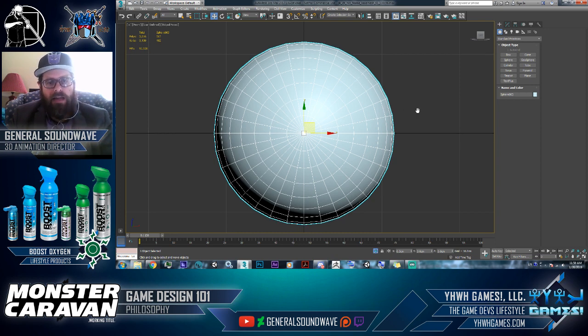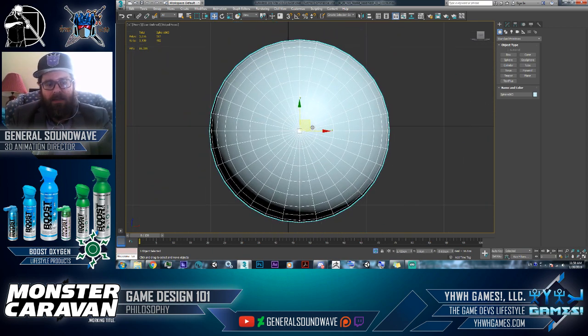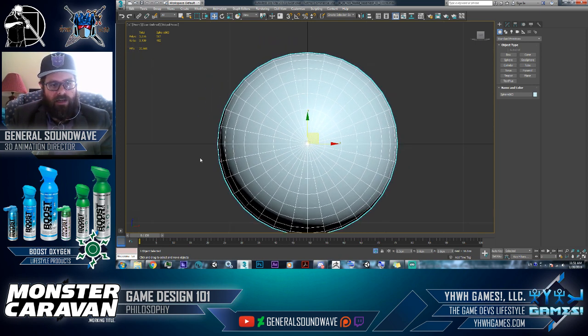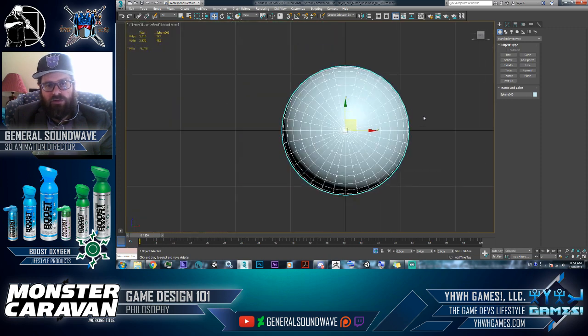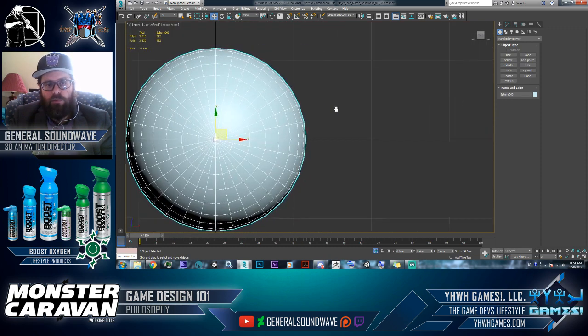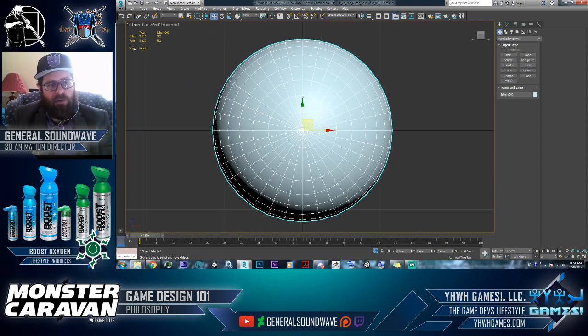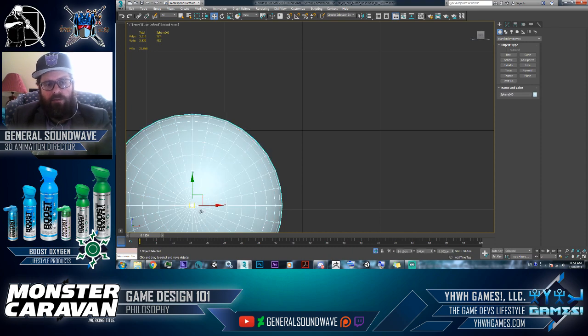All right, so now to pan, to move the camera. Now I'm not moving the object. This is moving the object. Now how do you know when you're moving the object or you're moving the camera? Easy. There's this grid over here. This grid is actually really helpful. If you press your middle mouse button and start moving it, not wheeling it. Now if you wheel, it's going to zoom in and out, okay? But if you press it and move the mouse, you're now moving the camera. This is what we call the orthographic front camera because I'm in this orthographic front mode here. Now if I'm moving the object, as you can see, the grid does not move. The grid does not move. So that's the difference between the two.